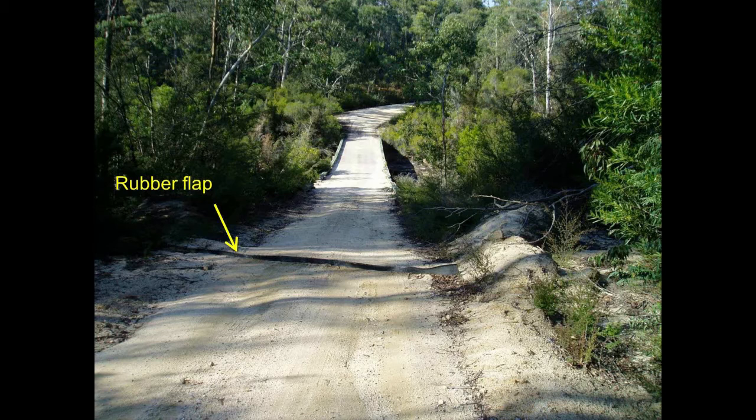Other things you might see in these scenarios are what we call a spoon drain or a C-channel, and they again have their advantages and disadvantages. Another thing to point out here in this slide is that you can see the rubber flap here, and there's one up on the other side of the bridge. This is a stream crossing, and these are very sensitive, which I'll get onto in a minute, for creating issues for water quality. So it's very important that roads are drained either side of crossings, and we typically recommend that you do that between 5 and 30 metres away from the crossing on either side.